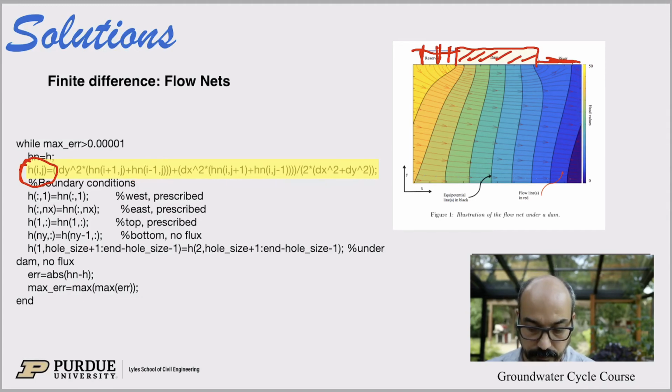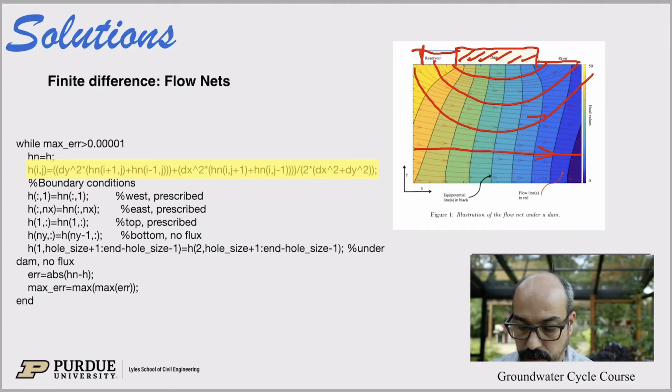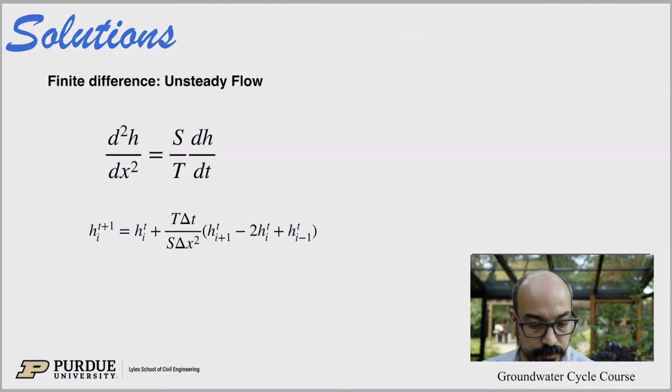And this is quite powerful, because now we can actually reproduce what we call a flow net. It's similar to a piezometric map, but it's a 2D slice, right? So now we can see the equipotentials going downwards here, and the flow lines, with the arrows. And again, this is very simple code, and this is exactly what MODFLOW, for example, the USGS package, does. I mean, this is exactly what they do with those engineering tools.